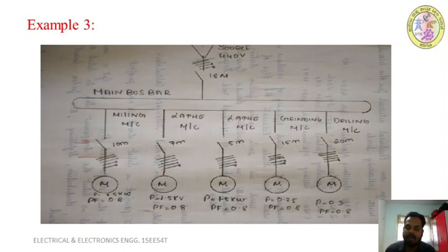In the main board we have an energy meter, main switch, indicators, main MCB and ELCB, and from that main board we take connections to the individual starter boards, and from the individual starter boards we give connection to the individual motor terminals. A different length of cable is required, depending on the location of your motors.